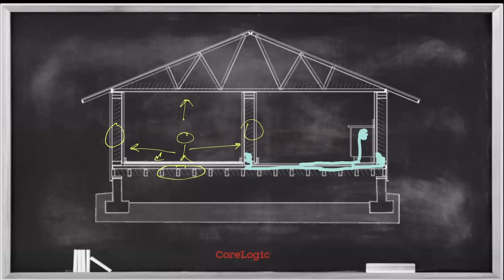And if the floor beneath the cabinets is wet, it's reasonable to expect that the wall behind the cabinets has also become affected. So now I have to check the wall plate behind the cabinets, the drywall behind the cabinets. If those are impacted, then it's reasonable to expect that the insulation in that cavity is affected. So you kind of follow my line of thinking there. You continue to do that until you find things that are unaffected.